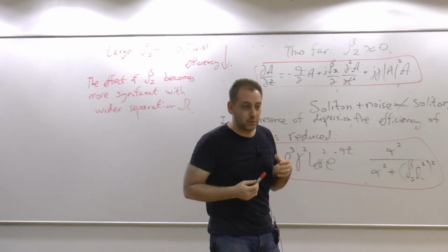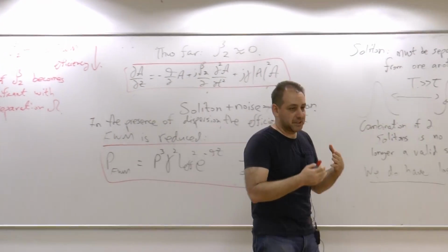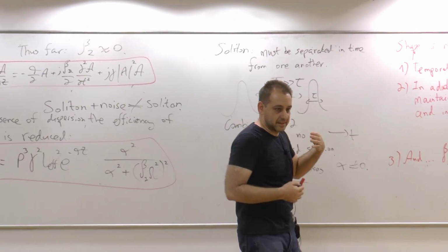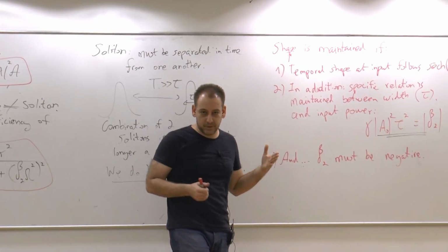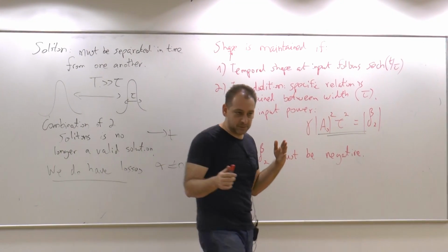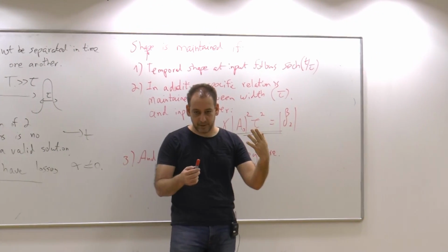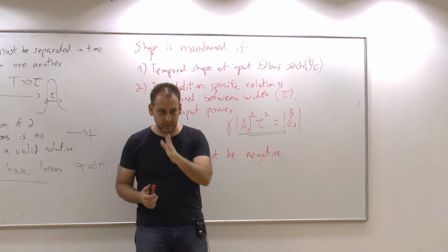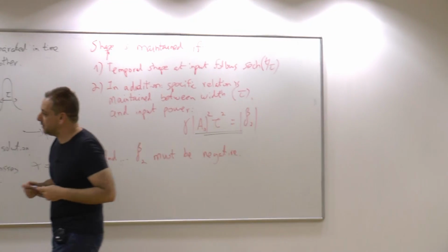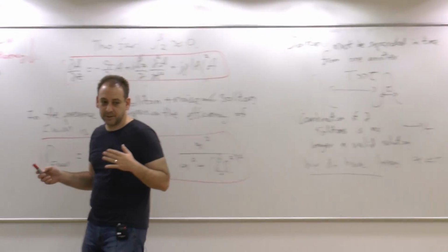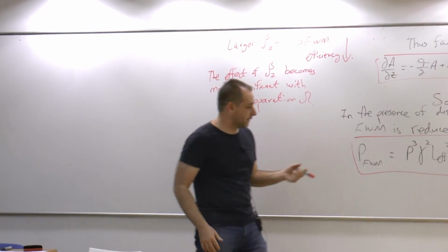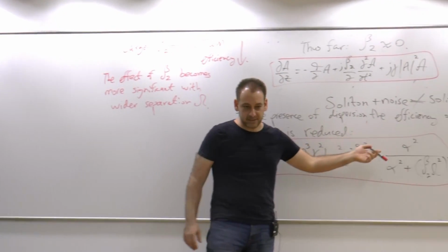Why? Because chromatic dispersion expresses just how different is the propagation of spectral components. If I move further away in omega in a dispersive medium, then the differences in propagation between tones number 1 and 2 and 3 and 4 become more pronounced. So if we have more dispersion, or if we consider this dispersion over a wider range of frequencies, the efficiency drops.